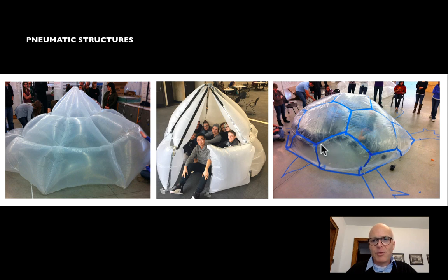You have to find a way to get into it without deflating the thing. In other cases, you can see that there are basically these giant air pillows. And the air pillows mean that the pneumatic principle is contained within the structure itself, and we can walk in and out without having to worry about whether we're letting the thing deflate or not.